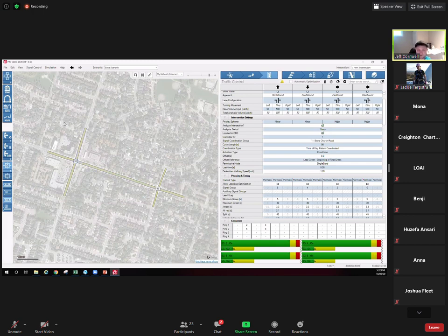So back to the route button. On top of all these different options here, you have this route button here. It says create a route for the optimization. So you've got to pick a direction that you want to go. So I'm going to pick the route button, and it makes this little S bend, if you can see my screen. I'm going to select this node, and then if you want to, you can select the next node, it will turn green, or you can just take it right to the end of your network, click, and you'll see that your route turns from purple to green.